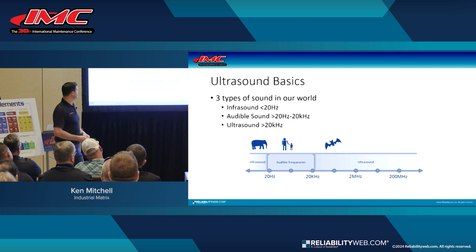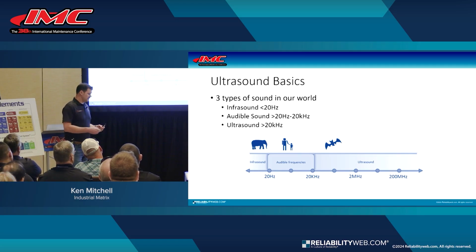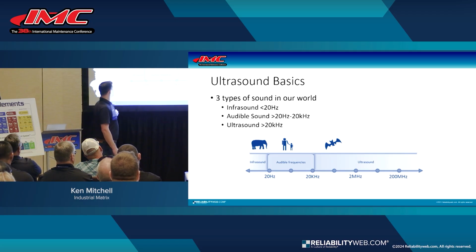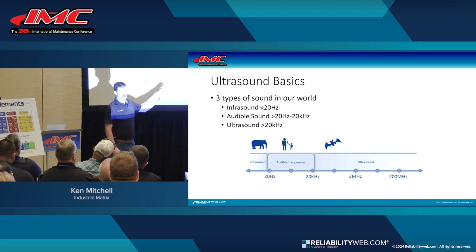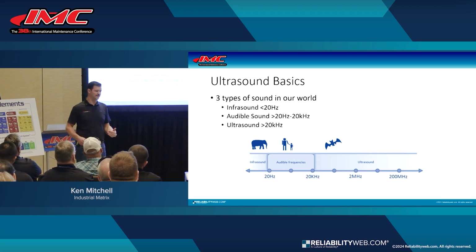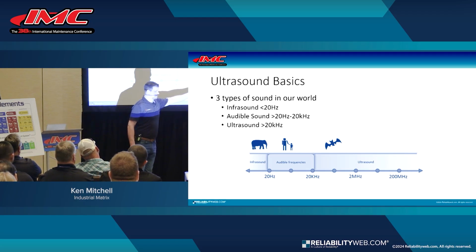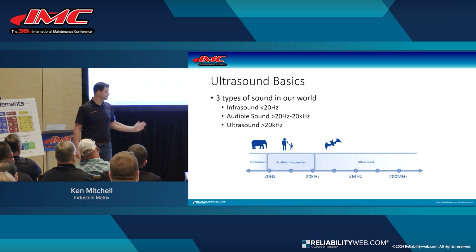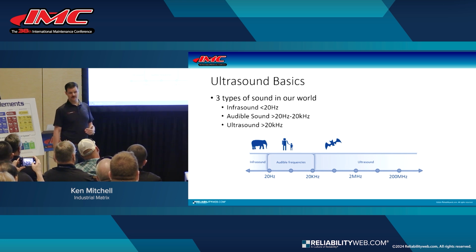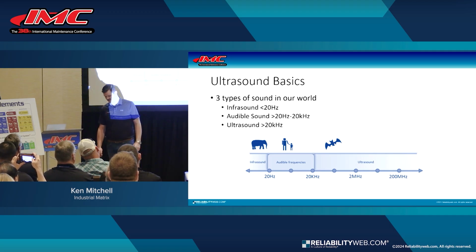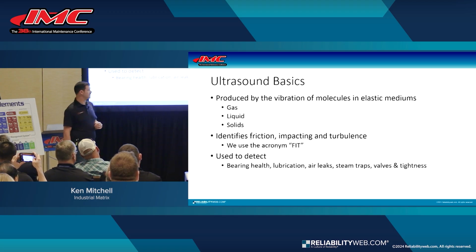I just want to talk about ultrasound basics as well. There are a couple of different sounds and frequencies in our environment, and I want to talk about ultrasound specifically because it is so important and it works as a good tool for us. When we look at human hearing, we hear from about 20 hertz all the way up to 20 kilohertz. As we get older, that 20 kilohertz comes down a little bit. Anything below that is known as infrasound, and anything above that 20 kilohertz range is the ultrasonic domain. We don't need to be super high frequency, but an ultrasound sensor is usually in and around 30 to 40 kilohertz, depending on the OEM and the brand of ultrasonic sensor, so slightly above what we can hear.